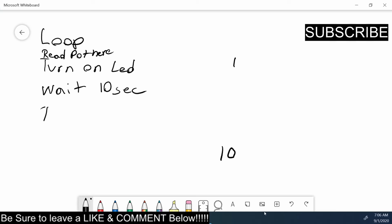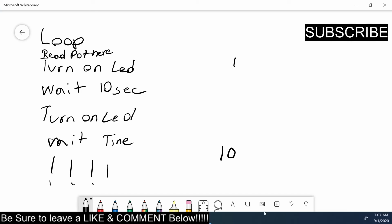If I turn on another LED in the loop and I do a wait time, and then I continue that on, and I do 6, 7, 8 LEDs, and I have a program with all the wait times that take a minute or 2 minutes to run, it's only going to read that potentiometer value one time at the beginning of the loop. So in order to make adjustments, I have to wait for it to go through the whole loop.